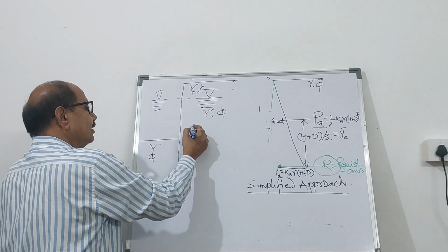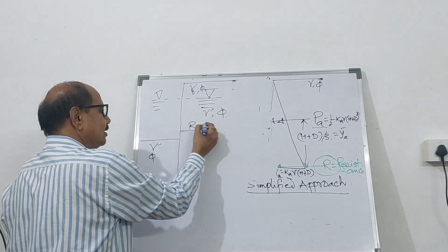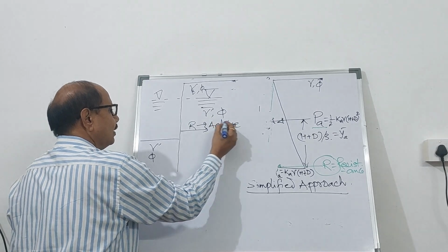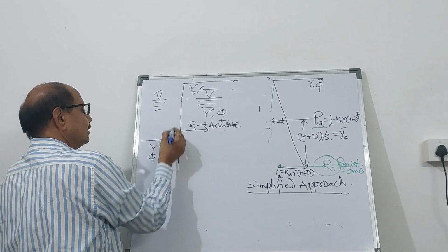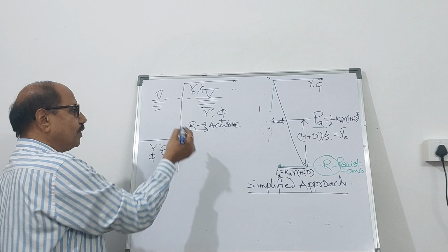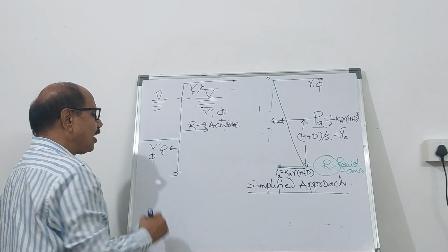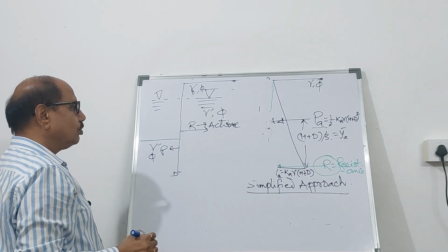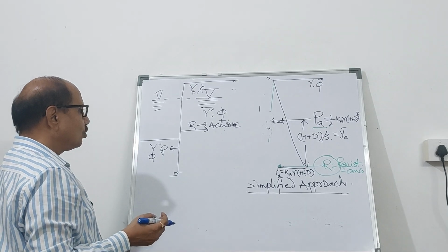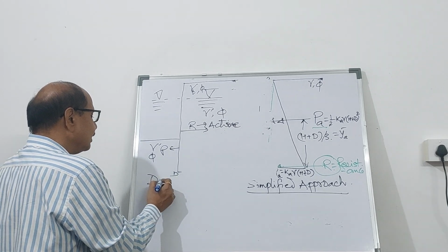But this side, we assume on the right hand side, so right side, it will be active, and left to this side below the dredge line, it is going to be passive. So the pressure distribution, easily you can draw it, taking the moment about the bottommost point and equating it to 0. The algebraic sum of the moment about B from the equilibrium conditions will give you the value of D.